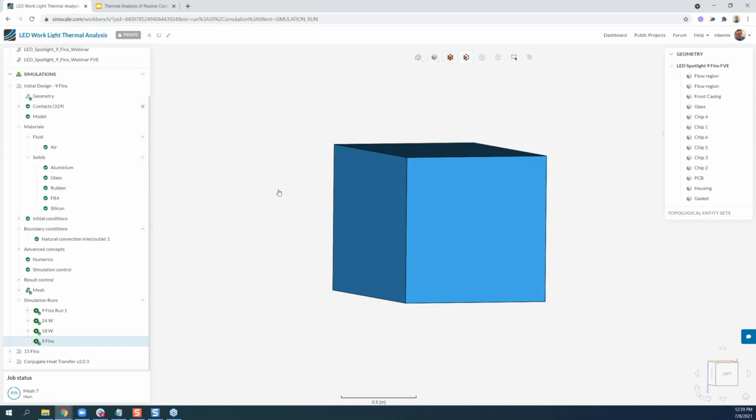Excellent. Then, can we also use particle trace for the evaluation? Yeah, absolutely. A particle trace is if you're just following a single particle through the system. Usually I put those at the inlet. I didn't set it up for this model, but you could put them at the inlet where the air comes in.